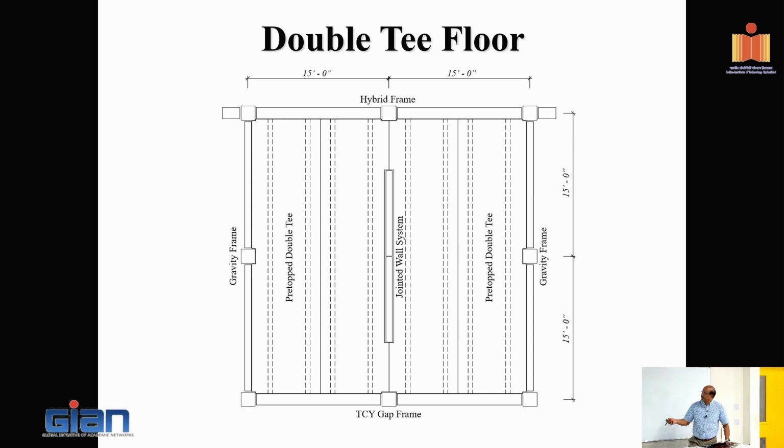In the other direction, the seismic resistance was provided by these 2 frames, but all of this has to go for the ride, including the jointed wall in the out-of-plane direction. In the opposite direction, or along that direction, the horizontal direction if you like, the wall was not connected to the columns. There was a connection between the floors and the wall. How is that connection? Yeah, I'll show you. The seismic load was transferred through the connection.